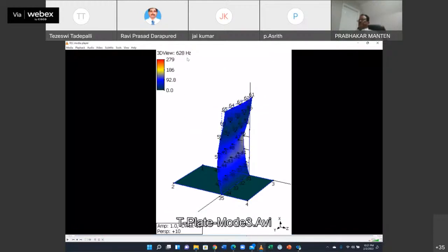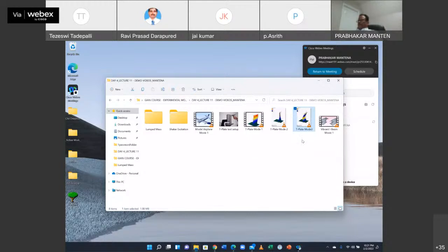First bending mode was 71 hertz. Pure bending. It's bending back and forth. There's a node point here. You see that? So anywhere in this region. Then a third bending. We captured one more, I think up to 3 or 4 more. So this is actual work done on a modal analysis, the modal pattern completely. And these people sent us some, Vibrant Technologies.